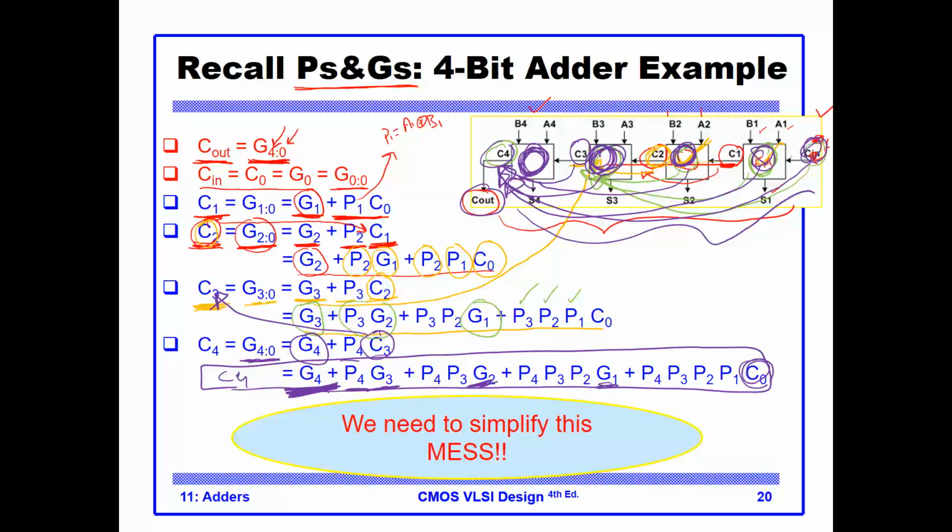Okay, so a good example for this case, for instance, if I have, let's say, A equals 1, 1, 1, 1, and B equals 0, 0, 0, 0, and Cn as 1. Watch, P1 is 1, P2 is 1, P3 is 1, P4 is 1.